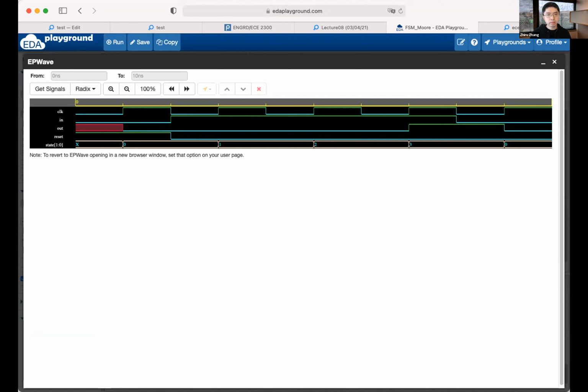At each clock cycle, initially it's don't care, it's not initialized or reset yet. So we have the synchronous reset here. Here there's a reset. Look at this, it's synchronous because we only reset the circuit at the triggering clock edge, in this case the rising edge. Before the rising edge, the state is not initialized. After the rising edge, it's initialized to the init state, which is 0.